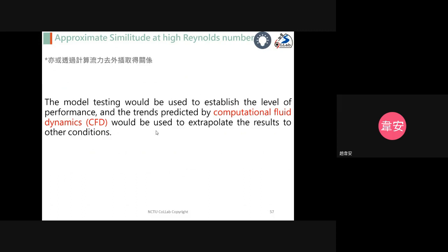usually we would like to have the dynamic similitude, and have the Reynolds numbers equal and try to predict the prototype performance for some dependent pi groups such as the pressure coefficient, the force coefficient and the shear stress coefficients.